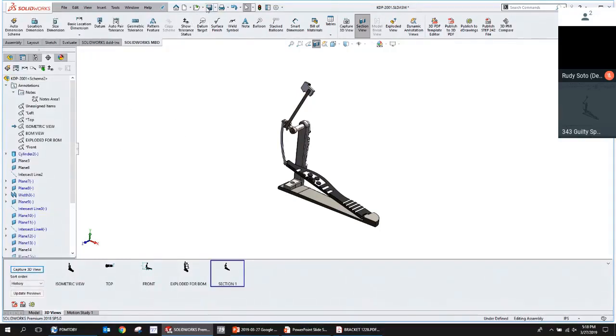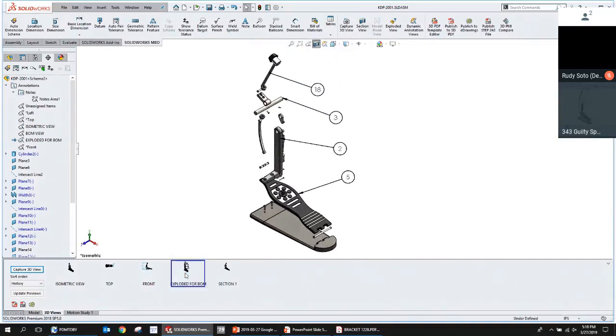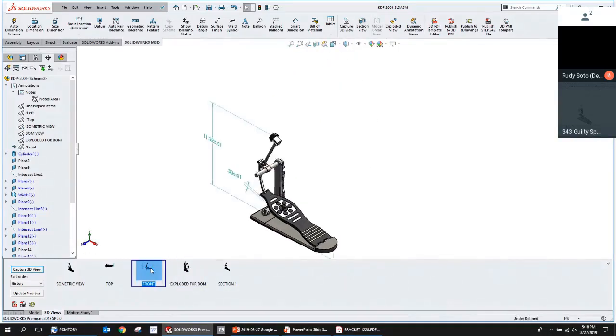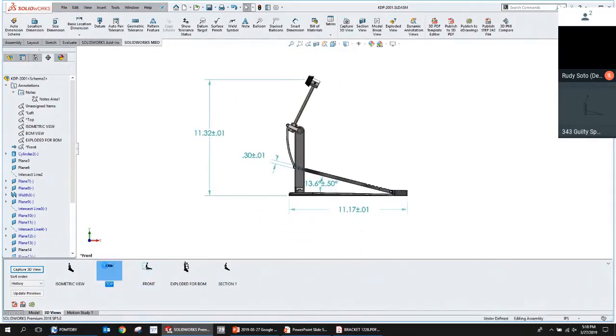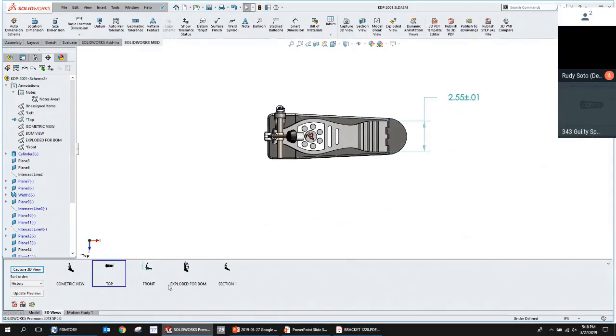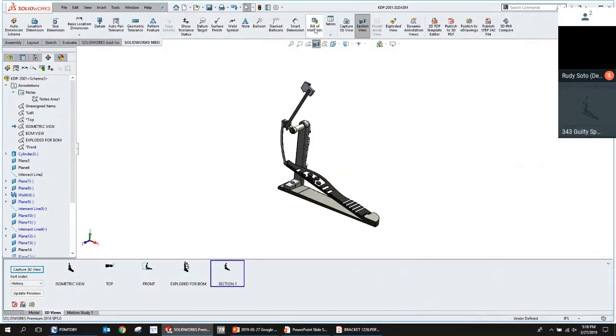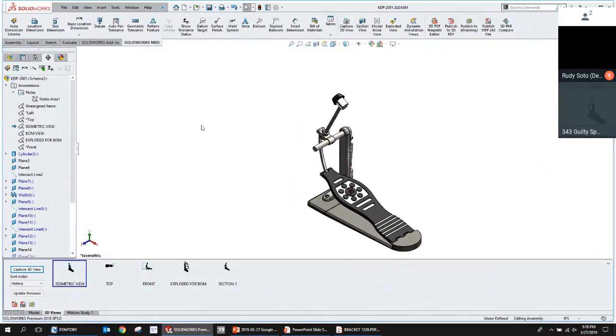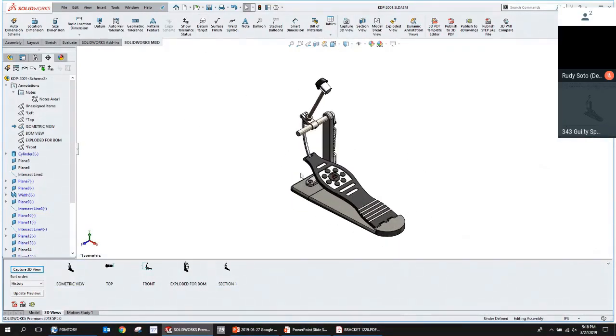All right, I think it looks pretty good. And now let's bang that out. So basically that's what you do. All you have to do is grab a section view. And the trick here is when you're double clicking through these views, this should be more or less what you get in the 3D PDF. So if you want to test something, like you see right here, the section view tool is not turned on, but then I double click here and then it turns on that tool. So if you want to double check that, that's how you can validate it before you actually create the PDF.